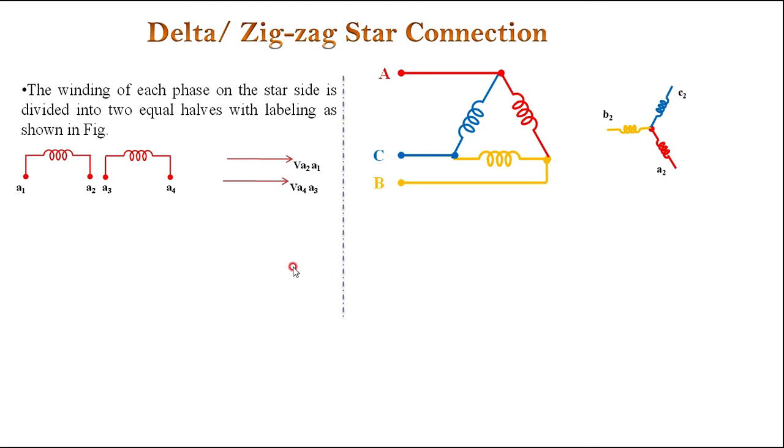Now, the other parts of the windings of A, B, C are connected here, with the same phase displacement. Look here: the second part of B is in phase with this B2. It is in phase with B2, and it is maintained here. But instead of connecting here for a single winding, I am connecting all the three windings in the secondary. Then the second part of B is connected to the tip of B2.